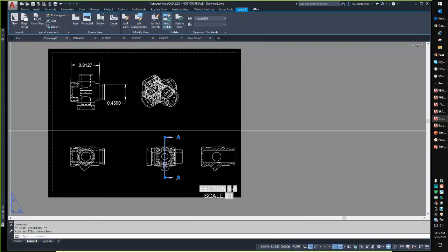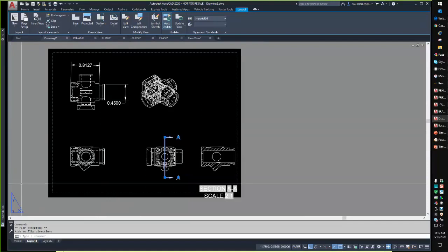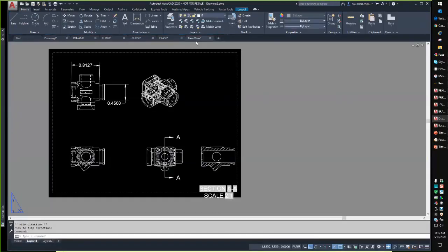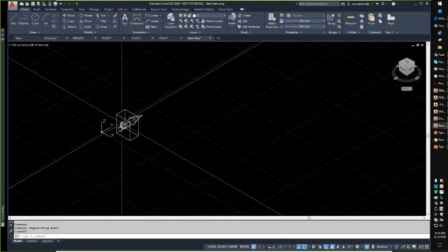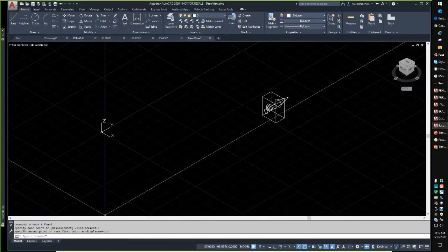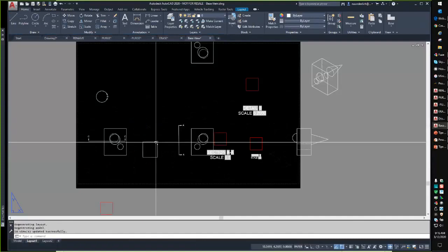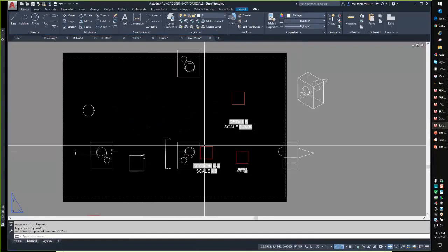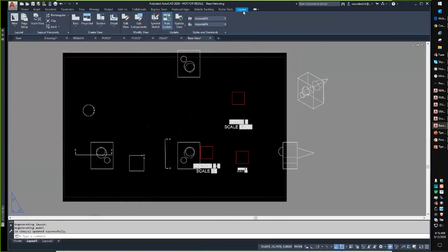If you move, change, or edit the object's location in model space, do the views change as needed? That is a very good question. Because this information here in base view is derived from here, I can go ahead and move this. All I did was move that. When I come back to my layout space, you'll see that it got real funky. Okay, so we auto update everything.